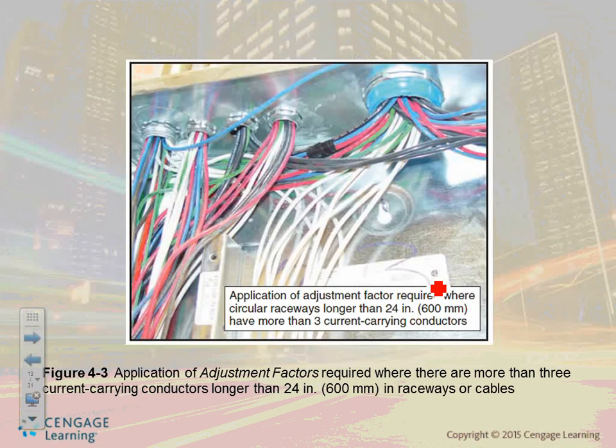Look at this. If your conduit, guys, is 24 inches or less, do you have to apply the bundling? No. We derate based on 3 conditions, gentlemen. Temperature, easy, right? If the temperature is other than 30 degrees Celsius or 86 Fahrenheit, you have to derate. Number 2, if you bundle, you put more than 3 circuits in one pipe. That's bundling. And number 3, you add more temperature if you put the conduit where? On a roof, commercial roof. You have to derate it based on temperature, but you add more temperature when you derate.